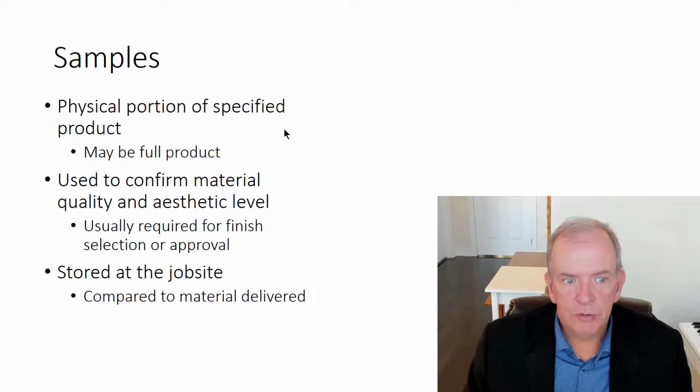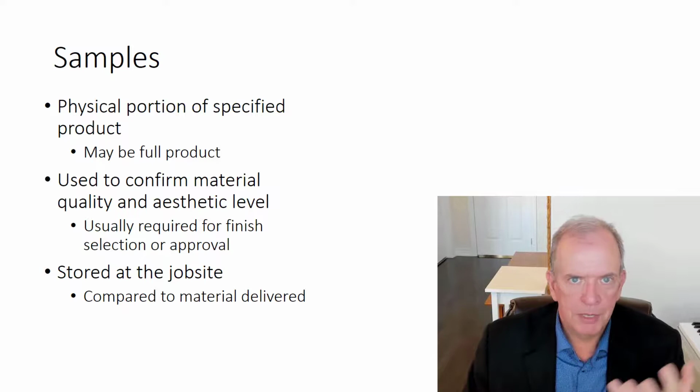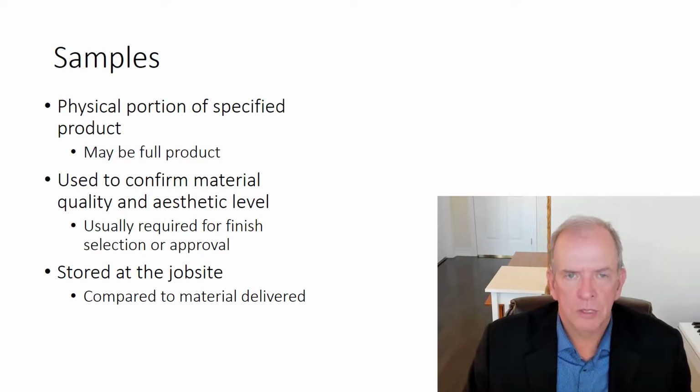So of course, then there's also, even keeping to the same theme, samples that you have to provide. And in some cases, mock-ups. It depends what it is. Just simple rebar, you're not going to need samples for, because the consultants know what it is and they've specified what rebar it's supposed to be. So that wouldn't be an issue. But you could have samples for the color of the window. So you might want a piece of the extrusion of the window that's showing, and maybe it's an anodized brown aluminum that would indicate what the color is of it.